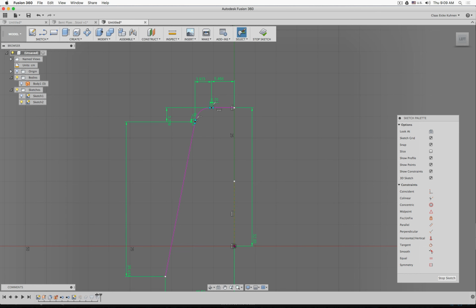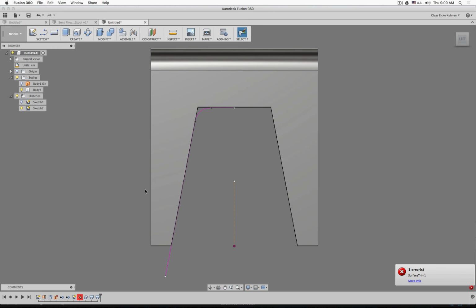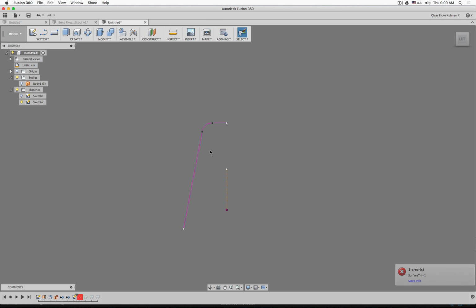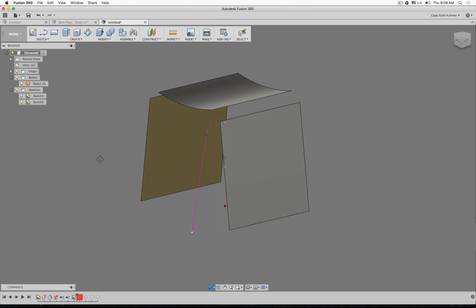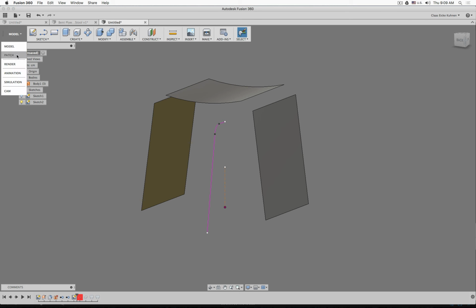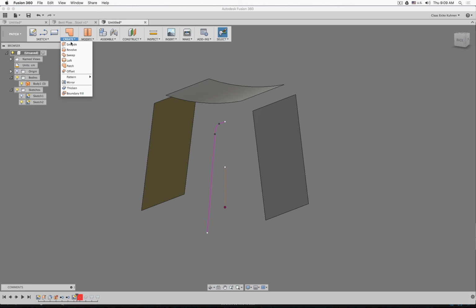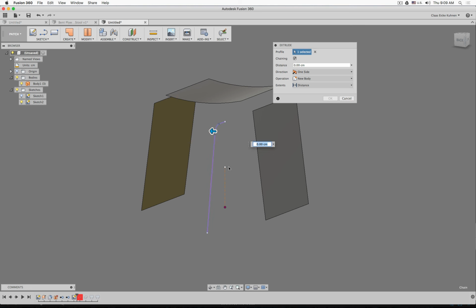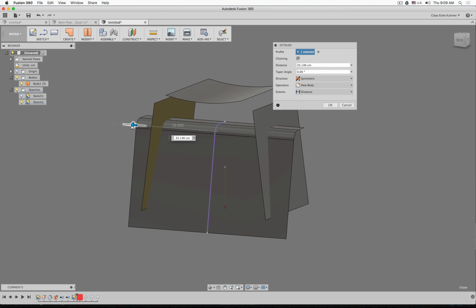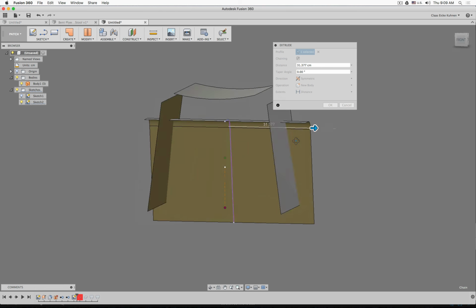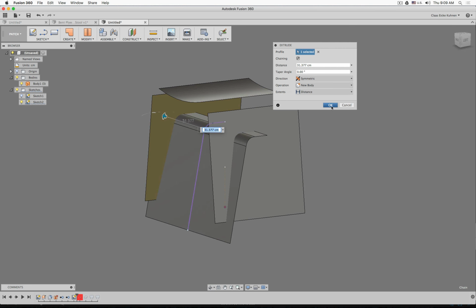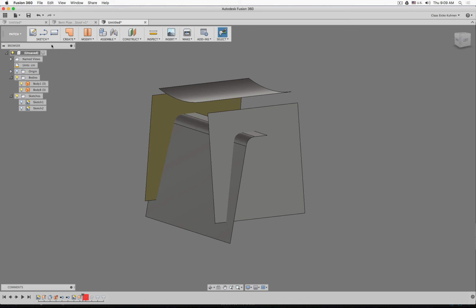So most of these commands actually will fail because when we click stop now, here the trim command says, what the heck? And that's because there's not a complete sketch anymore. And that's fine. So what we will do now is patch, extrude, and then symmetry, and we simply extrude and overbuild. So you see these surfaces are intersecting. Click OK. Now we have half of it.